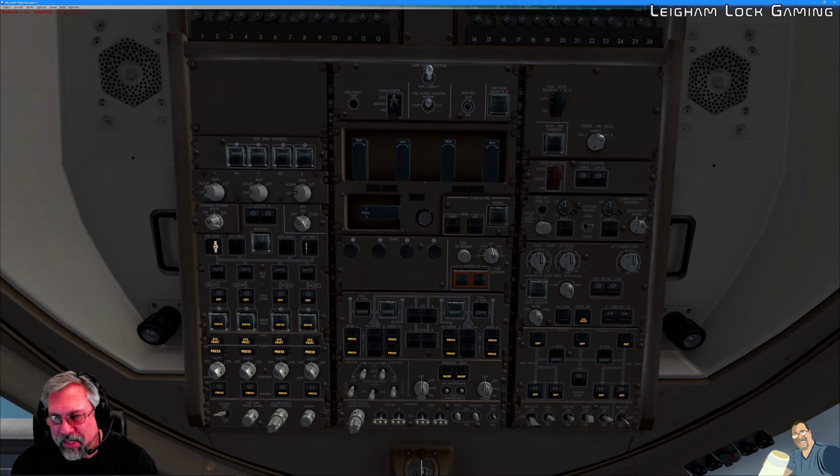From here, since we are inside the cockpit and doing work, thanks to Doofer 911 and some of the videos that he's put together, typically we want to go ahead and turn on the navigation lights now, and that just lets ground crew and personnel outside the aircraft know that there is somebody on board and the aircraft is likely in the process of being started up. So we've done that. From here, we want to go ahead and get our inertial reference system turned on. We have 3 redundant systems here for the IRS. I'm going to go ahead and turn those to the nav position.